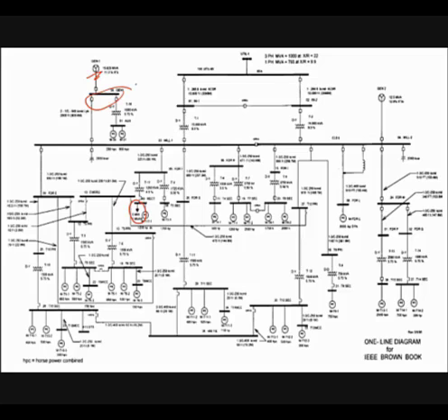So we want to know the power flow from the generators to the loads, as well as we can calculate the losses also. And we can determine the voltage at each bus. So that's why when the system is bigger, you cannot do load flow by hand calculation. Even for a small bus system it's quite complicated to calculate the load flow.